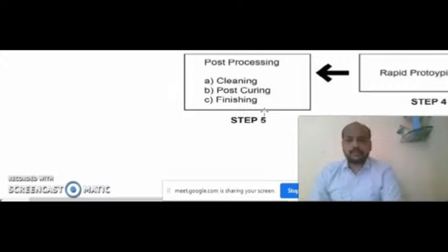Actually, you know about curing time. You might have studied this curing time in the casting process. The time required for solidification of that model is called curing time. So you have seen that curing time concept in casting. It must be solidified properly, otherwise its shape may change or it may break after 3D printing.